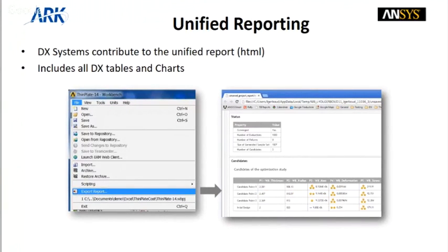Now once you are done with your simulation, you can export those results to attach into your reports. So how to do that? There's an option under File whereby you can select the export report option, and it will give you a PDF file which contains all the information about the analysis.